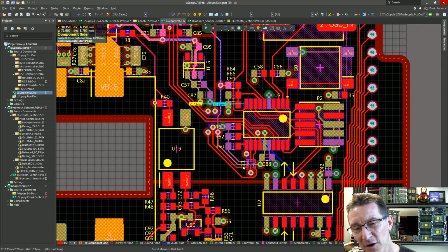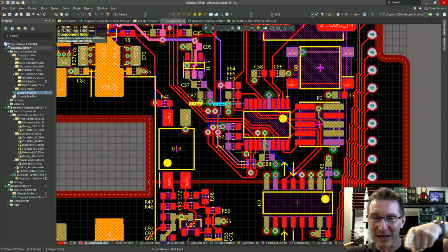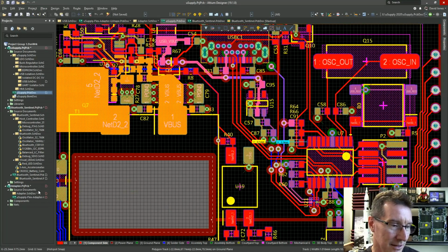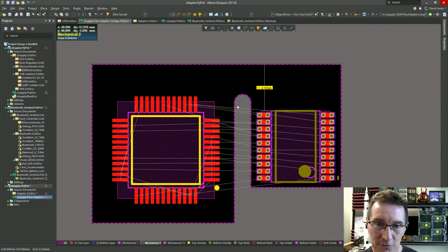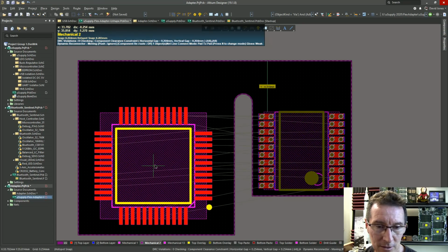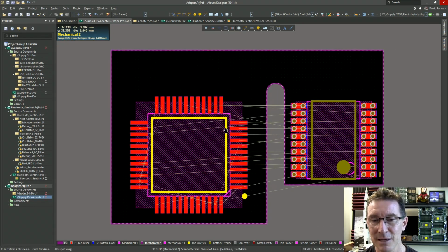So that will remove this crinkle, when you've got two intersecting radii like that, because this has to bend at that point and this has to bend here, so this will all be crinkly in here. To avoid that, we will add a bend radius in here, because this is where it's all doing the bending. I might even move this down a little bit, something like that. I'll just reroute that. Only take me 10 minutes.